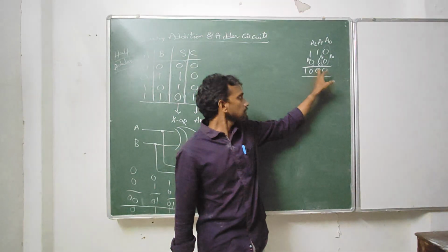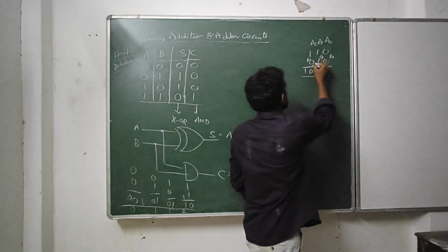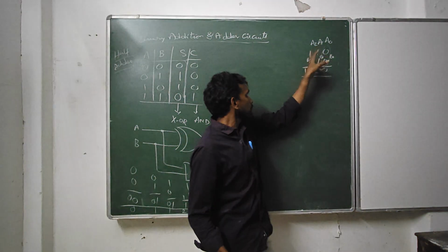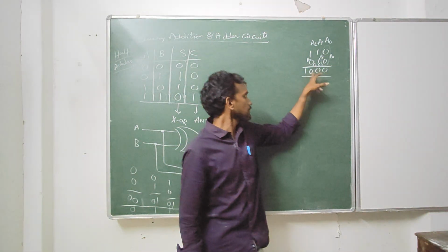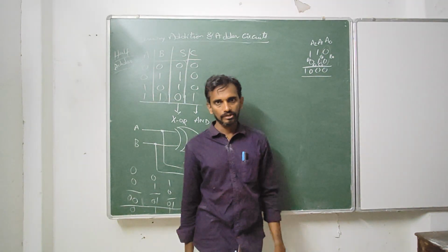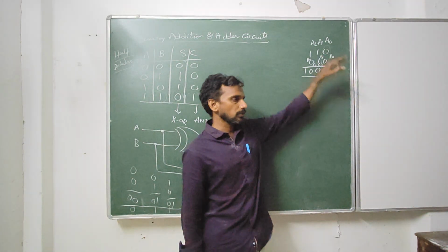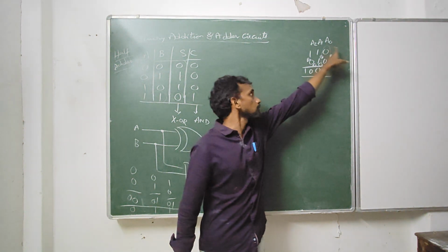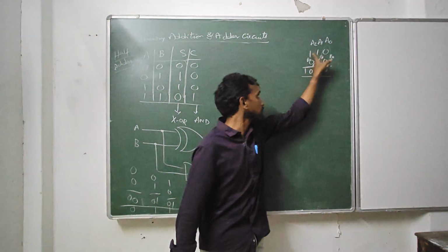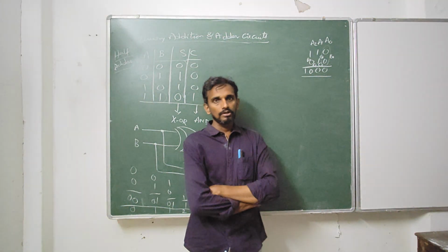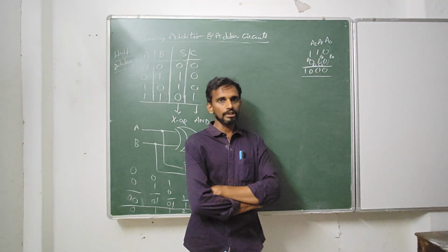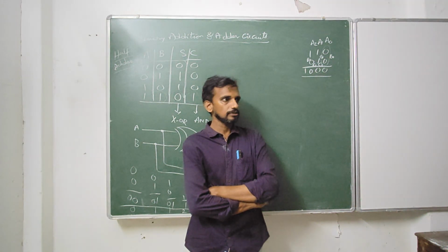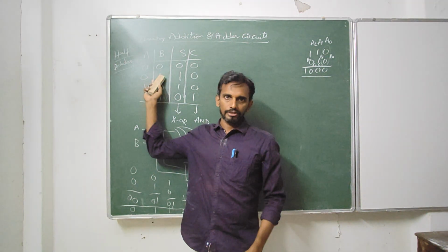You get the result sum, and you will also get a carry C2. Then you are adding A2, B2 and C2. You are getting a sum and also a carry. So at most you need to add 3 numbers. Sometimes you may add only 2 numbers, but sometimes you may need to add 3 numbers to complete the binary addition operation.